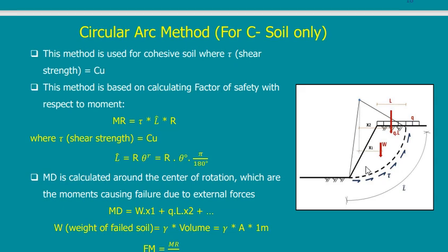It is shown, by the way, but you have to think of it. If this portion wants to slide, what is going to push it? What are the forces? Yes? These forces, but what are these forces? These red forces are the forces that are pushing. The own weight, this is the first one. So this W is the own weight of this wedge. It wants to fall down. So this wedge is pushing me.